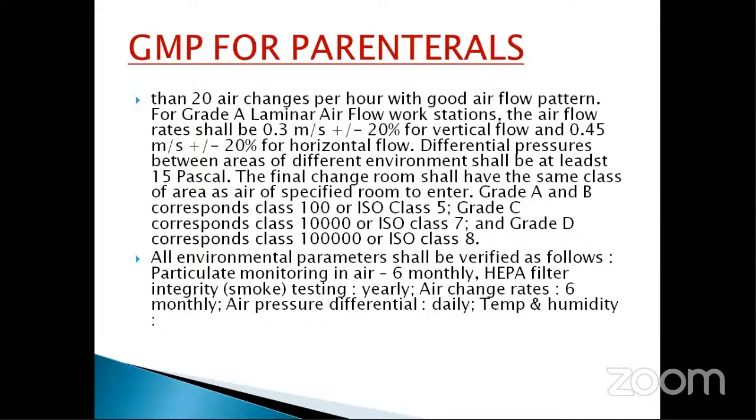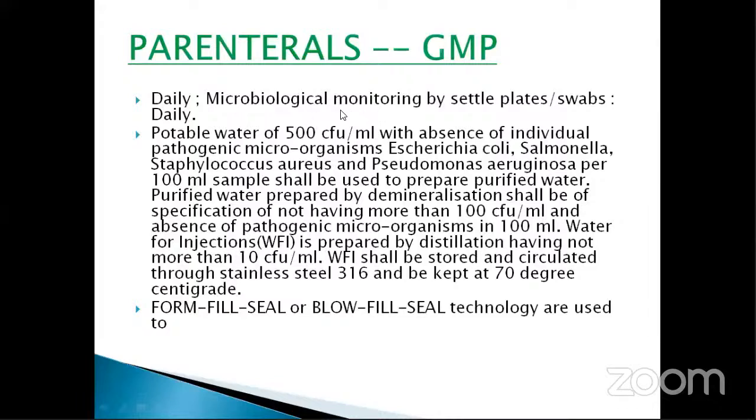Air change rates, you have to see 6 monthly, whether the air change rate which has been given here is maintained or not. But the temperature and humidity is measured daily, and you have to see. And at the same time, for microbiological monitoring by settle plate you have to provide proper agar media or culture media. And after a certain time, you will take the plate and see in the microbiological laboratory how much bacterial contamination is there. It will tell you what the air condition or manufacturing area environment is, how many pathogenic organisms are there. So this microbiological monitoring is done to see the microbiological contamination.